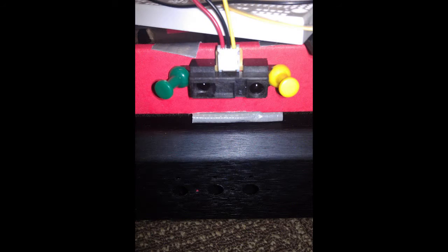Provided adequate power, the system should run indefinitely, provided it can return to the start of a course and it's not blocked in by walls. The system does have some bugs, however, and can occasionally slam into a wall. In this case, a manual driving mode with some commands we've defined can be sent and operated via XCTU or the web interface to get the rover back into a position that it can work from, provided the operator has line of sight.